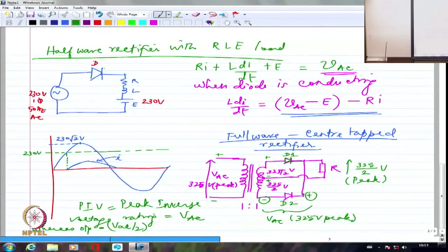So whenever I am worried much more about the voltage drop, not about really choosing a higher voltage rating for the diode, so typically power supply applications. In many power supply applications, instead of getting a 15 volts diode, if I have to get a 30 volts diode, the cost will not increase much. That's perfectly fine. But I will be able to save on the voltage drop.